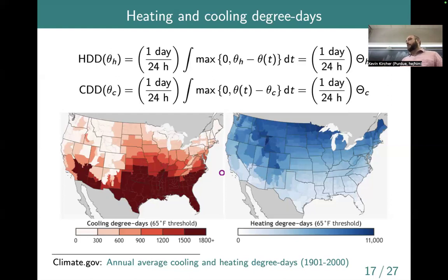And then maybe yesterday was a little bit colder, maybe it was 30 average. So we would get 35 degree days from yesterday because it was a little colder, and 30 from today. And then you just progress through your data set, your whole spreadsheet, doing that calculation and add it all up, and you would get, this is order of 1,000 cooling degree days for Indiana. And for heating in Indiana, it's probably an order of 6,000 or something like that, added up over the entire year. And the other question was, this is a very macro scale, very, very average.